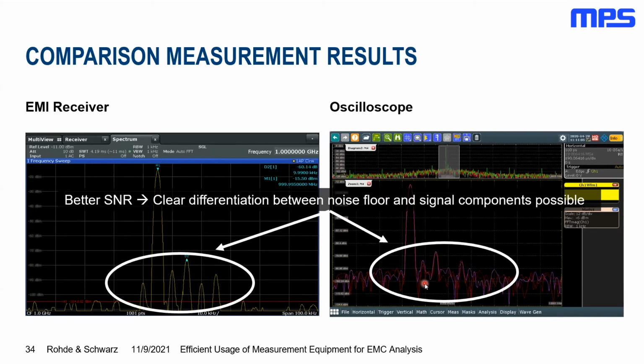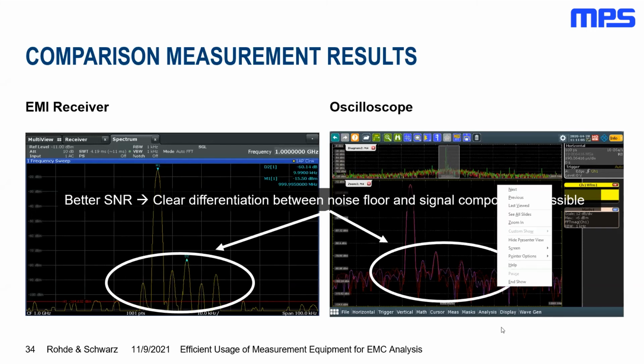If you have some more experience, you see there's no noise between these curves, so these are more or less CW signals that are always present, while for all the others we see some noise in the ground floor, so there's not a signal present at all times.